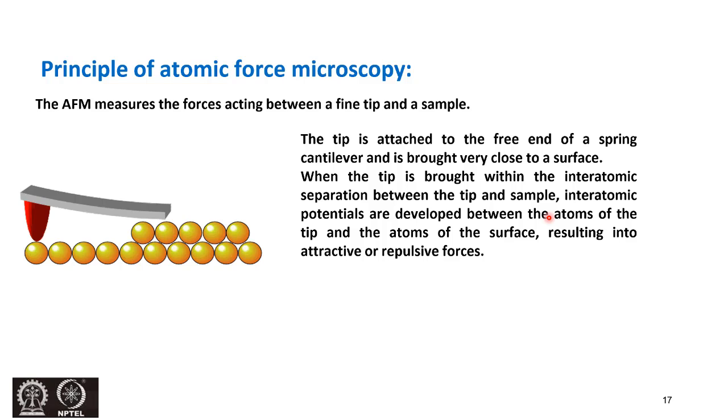So the principle is that we are measuring the forces which are acting between a fine tip and a sample. So the repulsive and attractive forces are what we are measuring. The tip is attached to the free end of a spring cantilever. So this cantilever is attached to the spring, and therefore it is moving up and down depending upon the forces, attractive and repulsive forces. It is brought very close to the surface. When the tip is brought within the interatomic separation between the tip and sample, the interatomic potentials are developed, and because of that, the atoms of the tip and the atoms of the surface interact, resulting in attractive or repulsive forces.